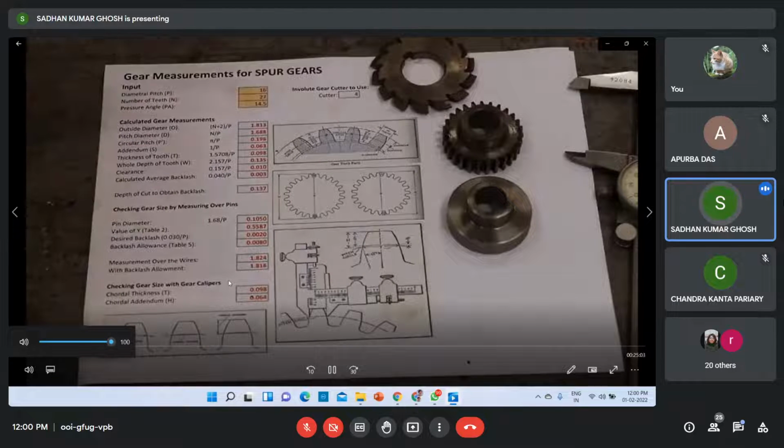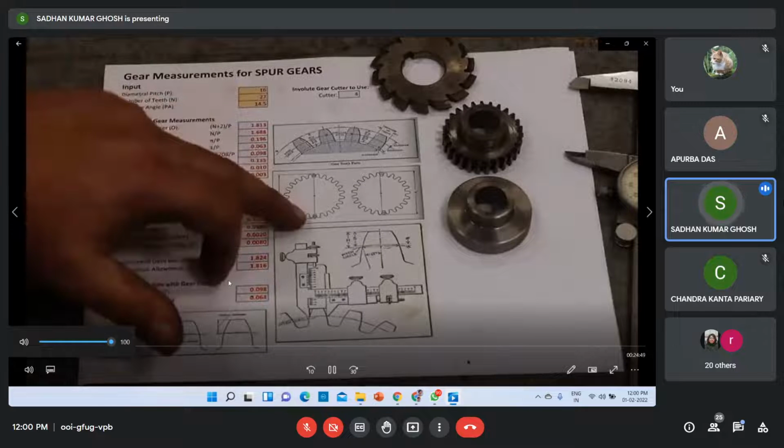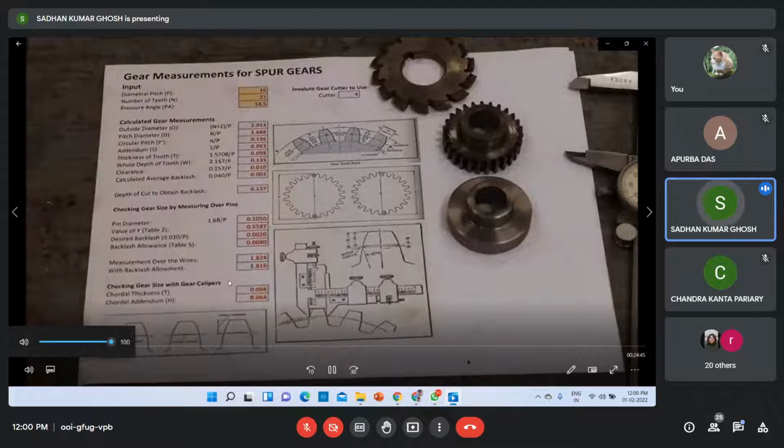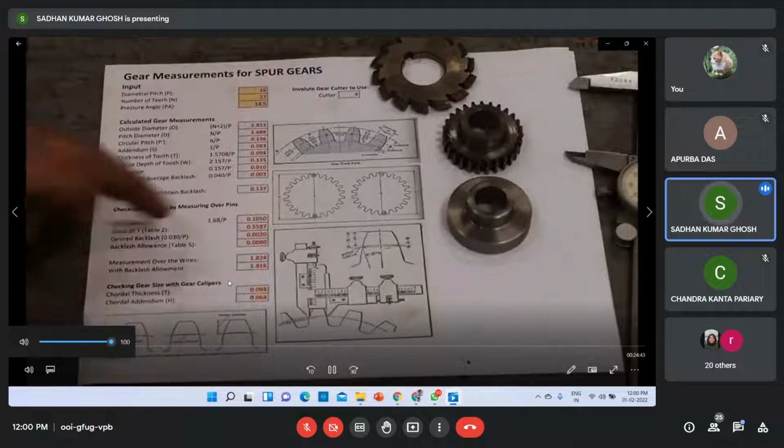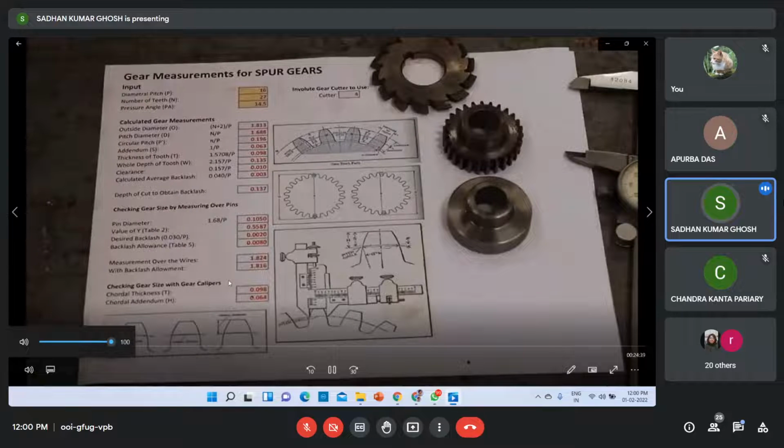What I'll probably do is set it up, take a 100 thousandths cut, measure everything, and then for the final cut, instead of just going off this number, we'll measure across the pins to get the diameter. It will tell you what size pin you need. We need a pin diameter of 105 thousandths, and there's again a formula to determine that.